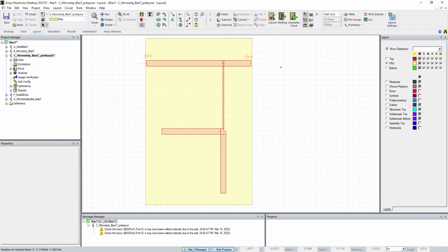So now we've kind of justified things left and right. Great. Now what about here? At first this is kind of how I had the board, but then I thought, well, what if I wanted the edge of the board to be here so I could literally solder a connector here, meaning that I'll have my port 1 RF, port 2 RF, but maybe this wants to be an SMA connector that we run off to the DC power supply. So let's go ahead and bring this edge to here. So how do we do that?